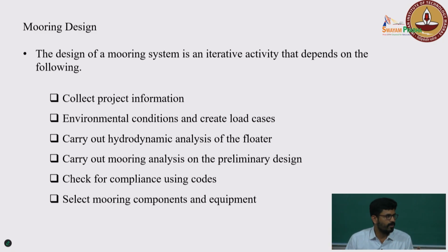It will always behave very violently, correct? So you must have the hydrodynamic analysis done a priori so that you will know how to position them, right? Because that comes as an input, because all your moorings are connected to your floater. When your vessel is going to move, that is going to transfer the load to your mooring, correct, and it is going to travel all the way to your seabed as well. So depending on your floating body also.